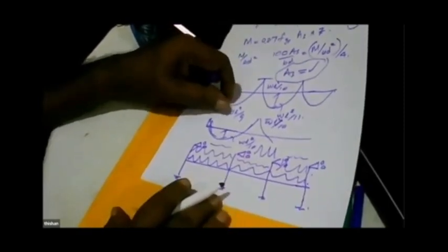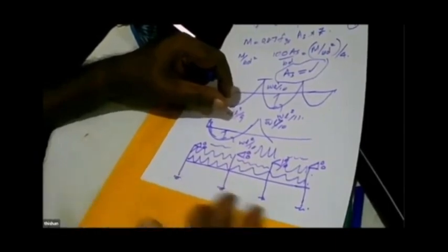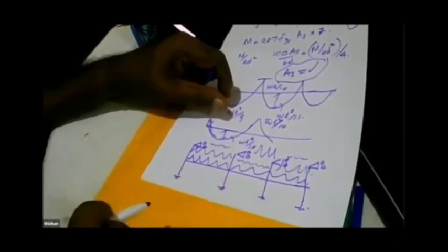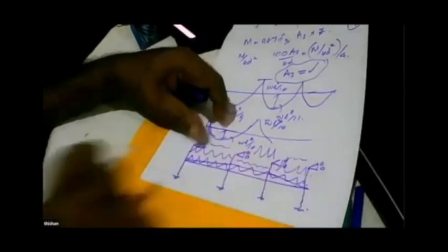And then find the bending moment diagram. And then I can do wonders. I can redistribute the moments just by looking at the moment diagram. I can decide how much redistribution, because redistribution means changing the origin of the bending moment. So it's very easy, and I can find the moment accurately. On the other hand, I can find the moment approximately and quickly do a design.